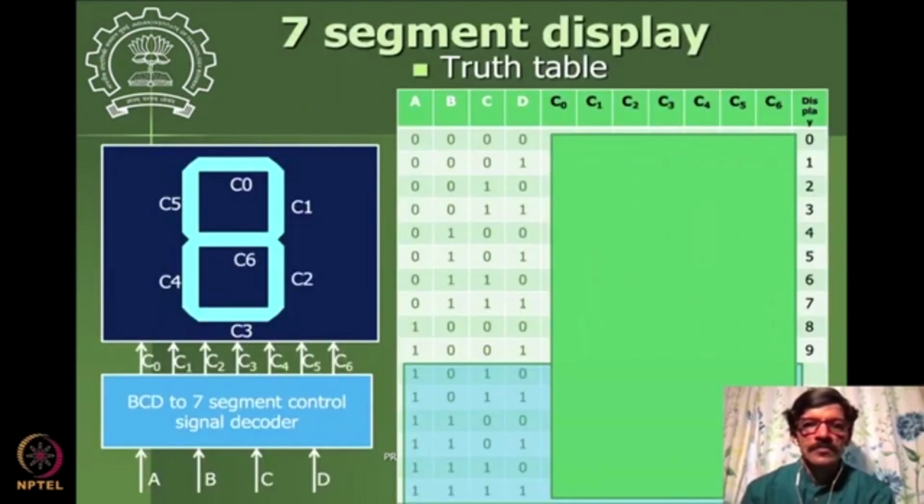Now there is another kind of output element called the 7-segment display. This is very important for mechatronics people, because a lot of these displays can be programmed with an understanding of the 7-segment display. This is just a combinational logic. If you want to display, say, 1 here, you need to see which elements of this display, which are basically LEDs, should be lit up to display 1 or 0 or whatever value you want.